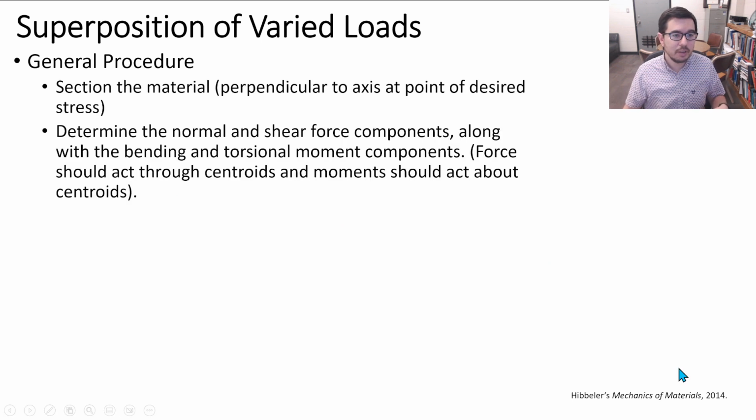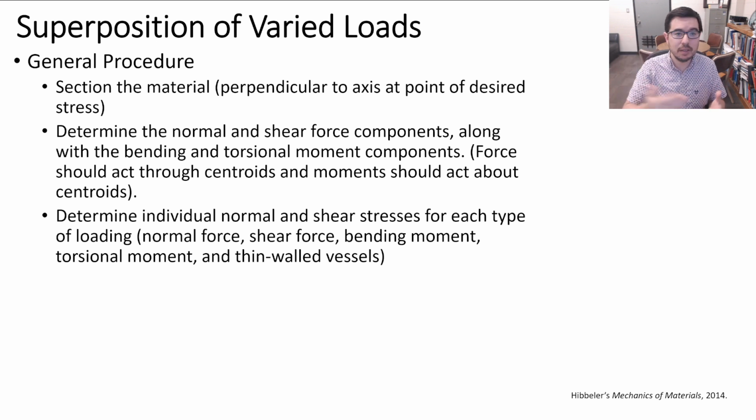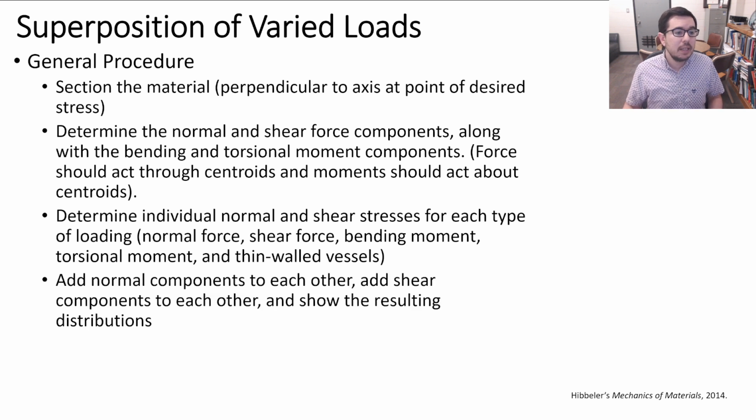Section the material. We're going to be looking at normal forces, whether or not they are inducing some type of normal stress, looking at shear force components as well, looking at bending, looking at torsion, okay, and then figuring out what the normal and shear stresses associated with these different types of loads would be. And finally, adding the normal stresses to each other and the shear stresses to each other.